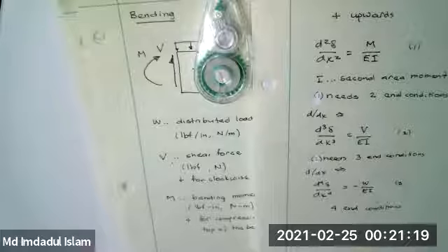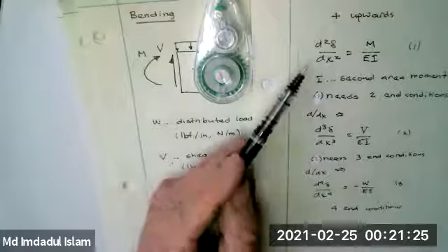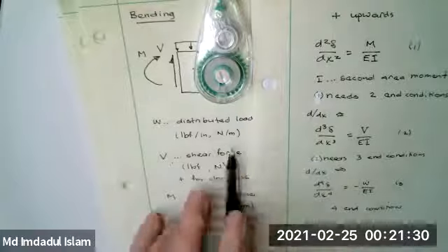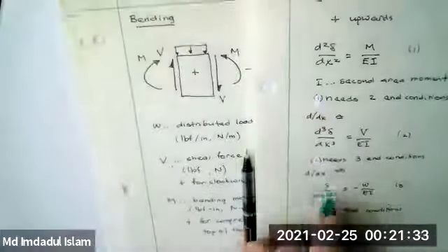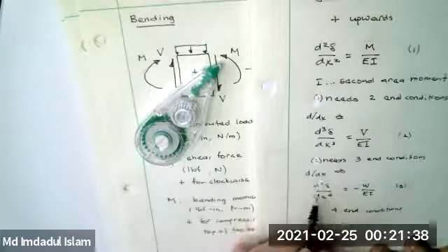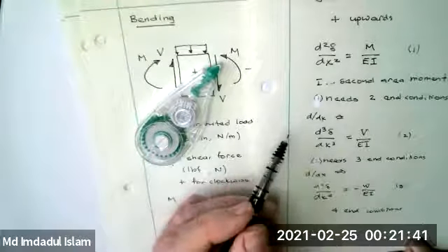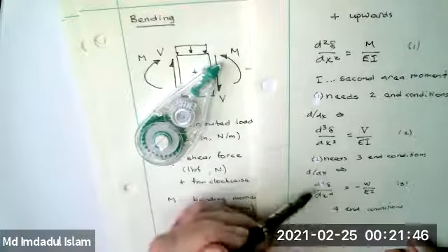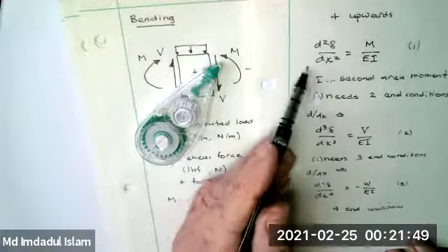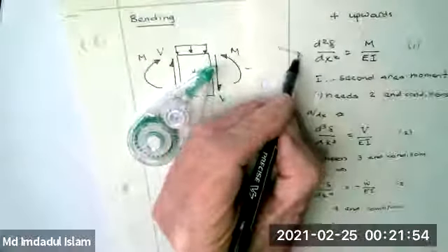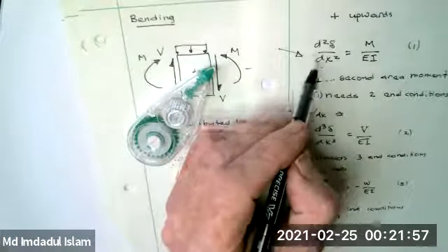Now, civil engineers have their own approaches to these things, a little bit different from mechanical engineers. But in mechanical engineering, the dominant stress is going to be bending, so you always have to find this out anyway. There is some body of thought that you should start with this, and then you don't have to worry about getting the bending moment. You're always going to have to get the bending moment. You're, in effect, going to get the bending moment when you come up with these end conditions. On the way to integrate this, you're eventually going to get to this, and then you're going to integrate this twice. I think you're much better off as a practicing ME to go get this M and solve this equation.